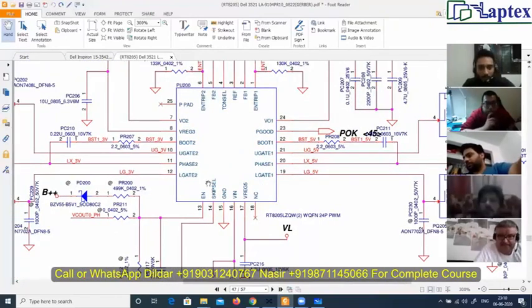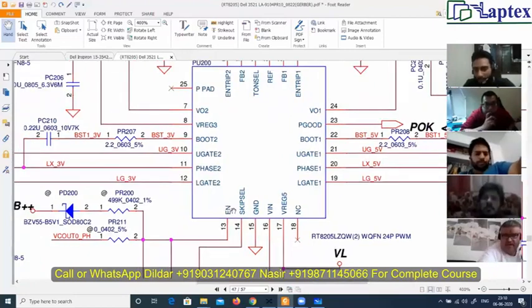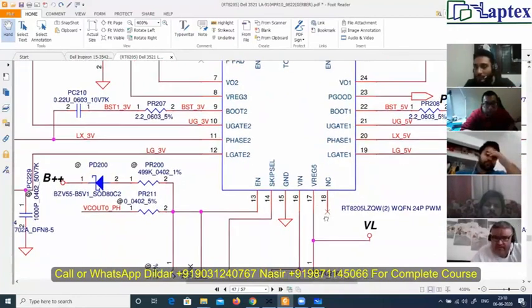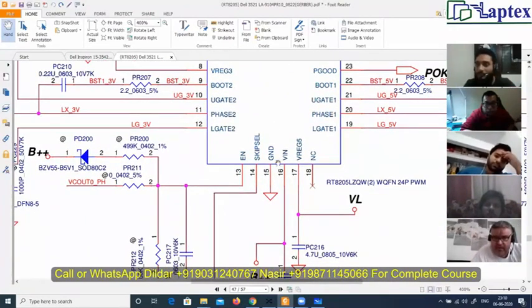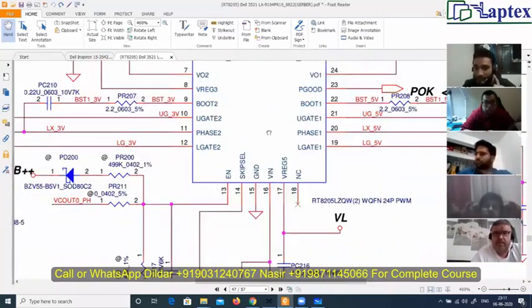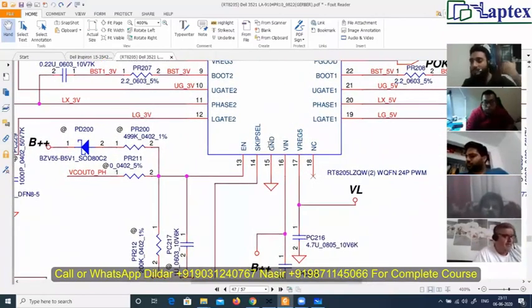So see here, this is the enable. This LDO enable is controlled by which signal then? VIN, directly by VIN. Are you getting the point? What I told you: the LDO enable signal will never come from IO. The LDO enable will be self-enabled or enabled by VIN.